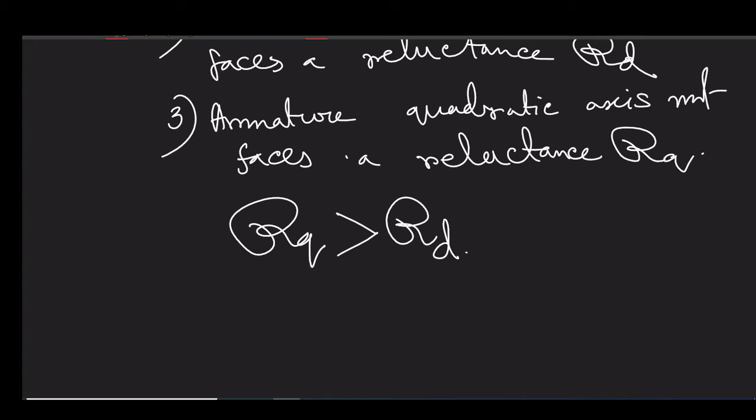It was very interesting that he suggested something that is known as two reaction theory. Instead of one armature reaction, let us consider two reaction theory.